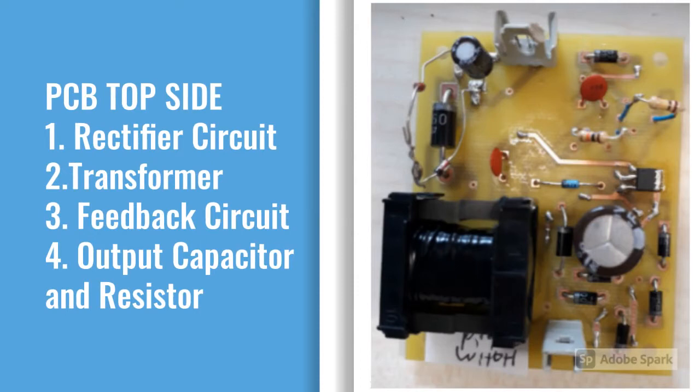My circuit consists of 4 different kinds of things. The first one is my rectifier circuit, which is a full bridge rectifier and a capacitor. My second kind of thing is the transformer, which takes that input and transforms the input to my primary power to the secondary circuit and the tertiary circuit. The tertiary circuit is controlled by 2 kinds of resistors, and basically they control my switcher, which is needed for the feedback. And my secondary circuit has a diode and a capacitor.